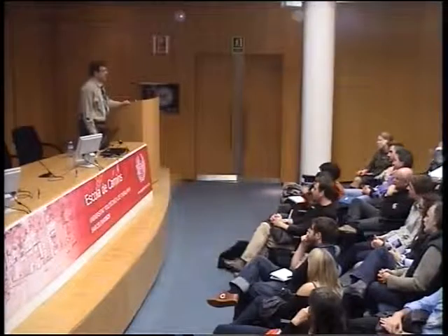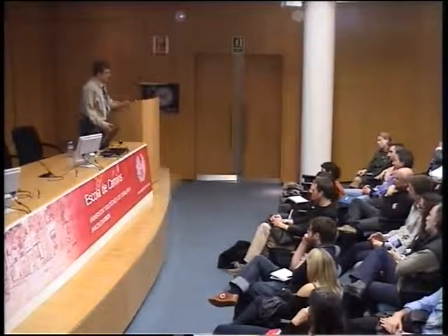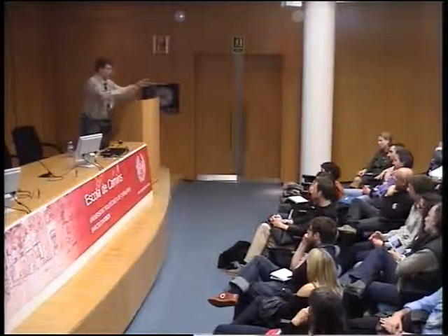In the smaller gravel bed rivers, you can enter the stream, bring a bulldozer, move sediment around, put stones in it, arrange things, try and create riffles. And if you are looking at a stream the size of the Wabash River, which also has, to a certain extent, a damaged ecology, none of that is going to work. And if you wanted to do something to try and improve the stream, doing something about nitrate inflow might be a lot better than trying to build various kinds of structures on the stream. So I would think that I'm not an expert on all, I know a little bit about a little bit, but I wouldn't think that if we have to intervene in a substantial way, that the way of intervening would be universal across the scales.